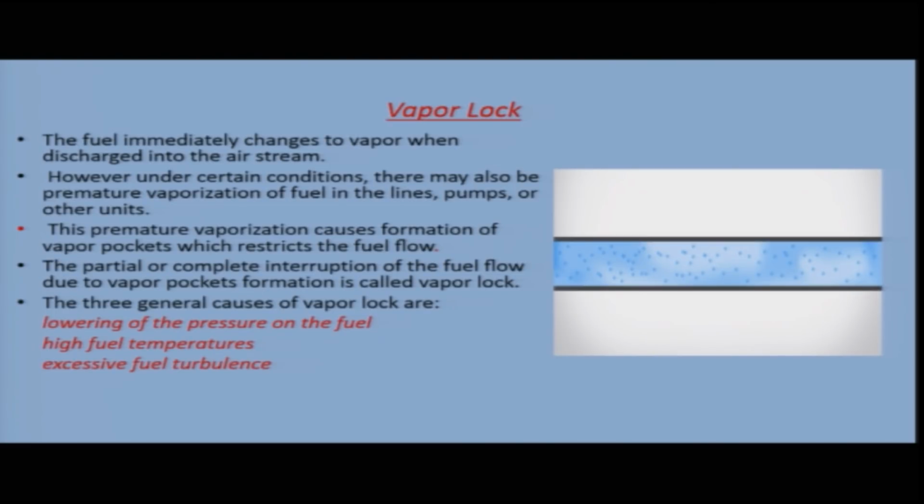We encounter a lot of problems because of vapor lock, especially in hot climatic conditions. So, we need to be careful. This is premature vaporization of the fuel causing vapor pockets in the lines or the pumps and resulting in fuel starvation. There are various reasons for vapor lock.